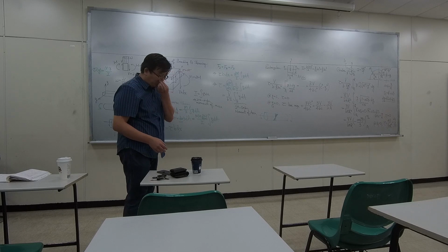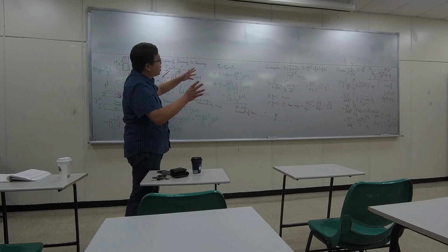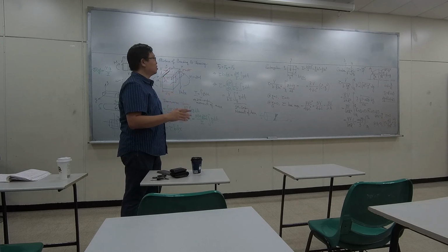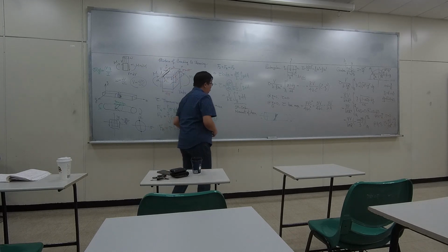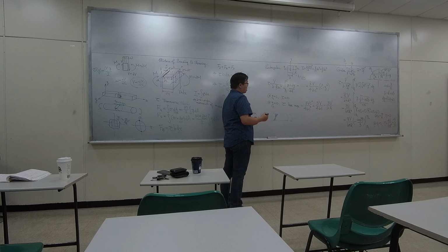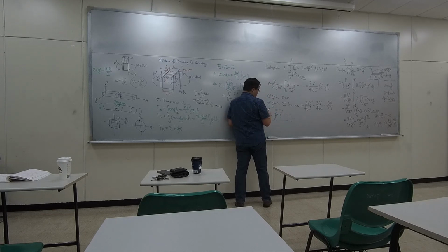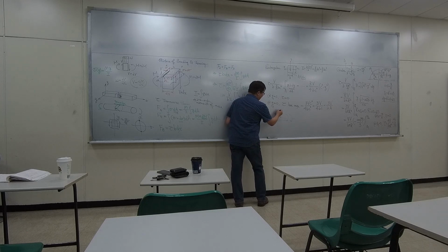So usually when we draw the shear diagram and the moment diagram, we care about what's the bending moment. And at this particular position, at the very top, the stress equals the moment times the radius over I. So from the shear diagram, we get the value of moment.